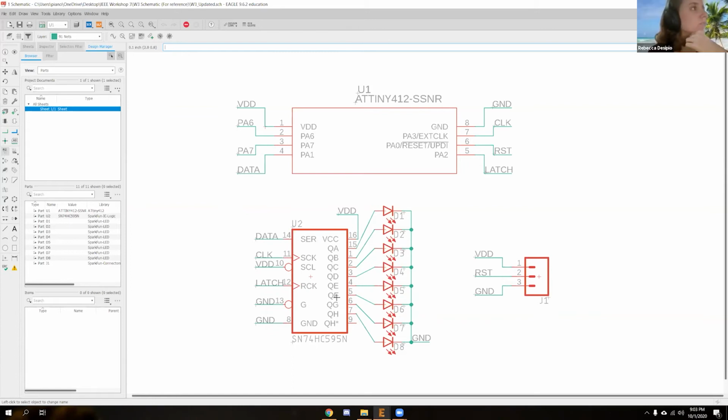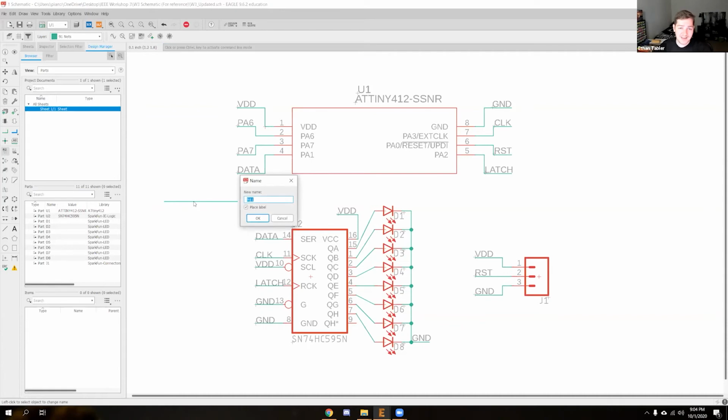Can you repeat what you did with the nets? Yeah. If I create, say, a new net, not really connected to anything, it's just there. You'll notice that whenever we named the other ones, it didn't prompt you for anything other than just the name, and it had a default, like N$17 or N$ something. If you go down to the name tool, and I click on this blank net that I made, this is N$1.